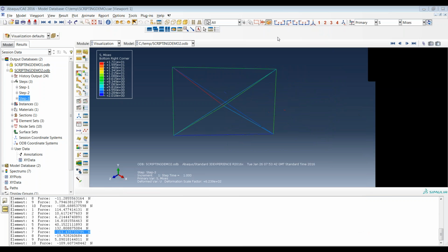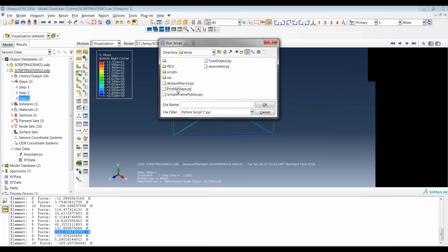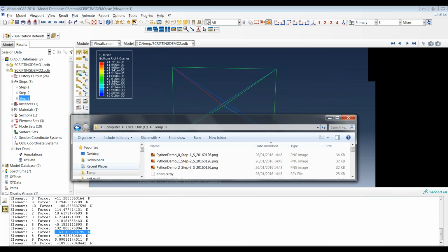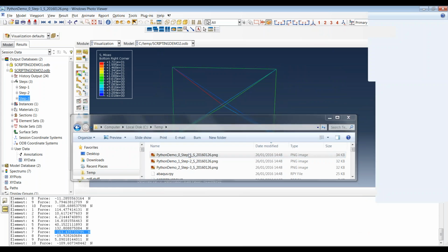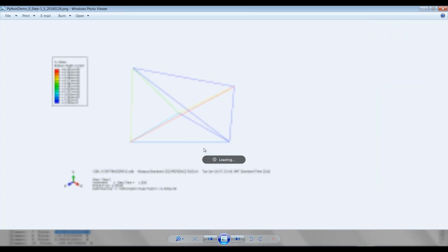If you actually turn on, for example, mesostress, then we can rerun the script. Let's call it again, Python demo. Right, then we'll end up with more pictures, and this time we can actually see the stress values under different loadings that I set up on this frame structure.